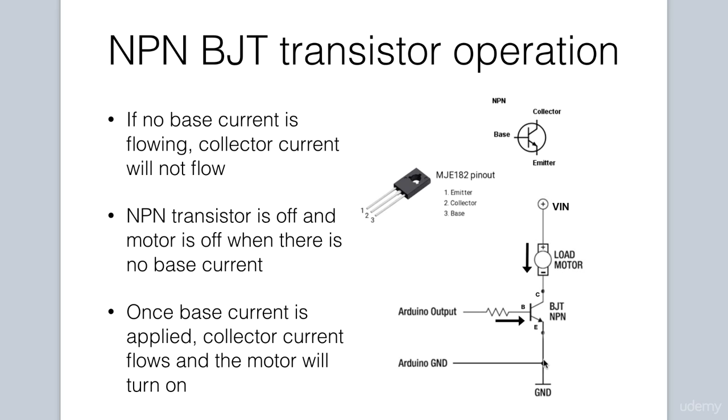You can think of the operation as a switch for our motor. In order to turn our motor on via an electrical signal which we can manipulate using the Arduino, we apply an analog voltage output from a pin of the Arduino to the base of the transistor. This effectively turns the transistor on, causing the circuit to be complete, and current will now flow through our motor, turning on our fan, down to ground. The fan turns on.